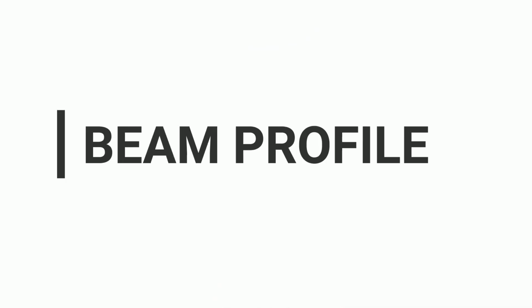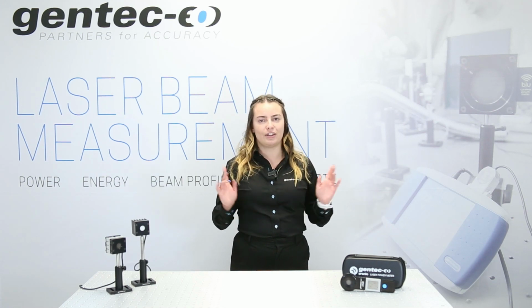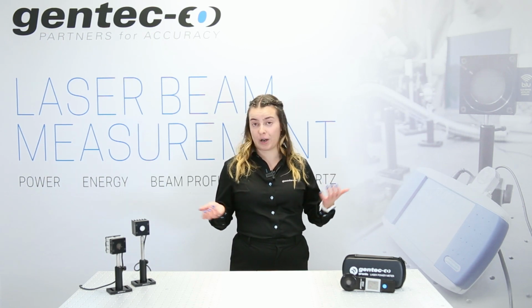Beam profile measures the power distribution in a laser beam. It is useful to know if the beam has hot spots where the power is concentrated and would cause unexpected damage to the material. One industry where beam profiling is often needed is a type of 3D printing called laser powder bed fusion, since powders need to be melted just right to get the best results. This means the power distribution needs to be adjusted. Some welding applications use some ring-shaped beams that need to be monitored to make sure they have the correct profile.